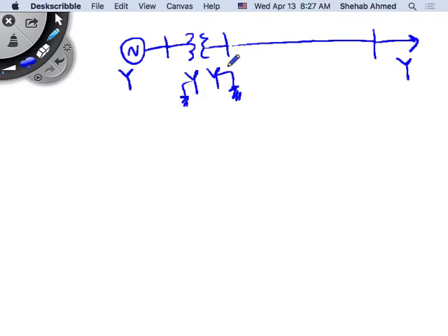So what does the positive sequence circuit of this system look like? The generator, the source, and if I give you the positive sequence impedance, you put it for the generator. If not, then you don't put it.